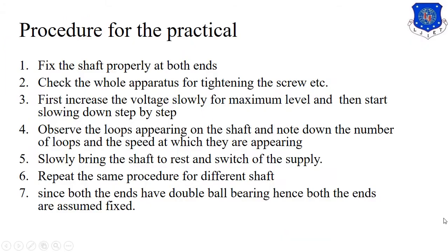Now, let us consider the procedure for the practical. So what is the procedure? First of all, we have to fix the shaft at both ends very properly, because when it starts rotating, it will be very dangerous for us to control that shaft.